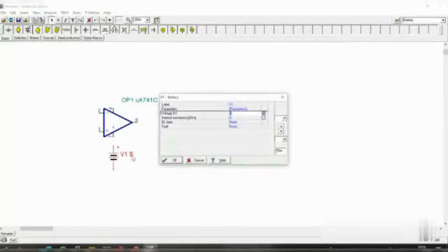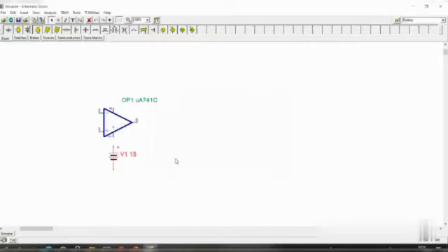So double click on this again, like the one I have done before. The battery parameters, the voltage value, etc. will open. So you can see that it is 5. Please make it 15. Okay, then OK. Nothing else is to be changed. Only the voltage we need to change from 5 to 15, that we have done. So that is like this.